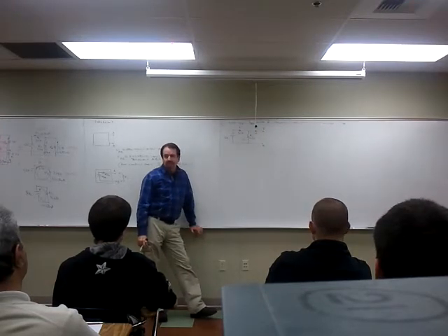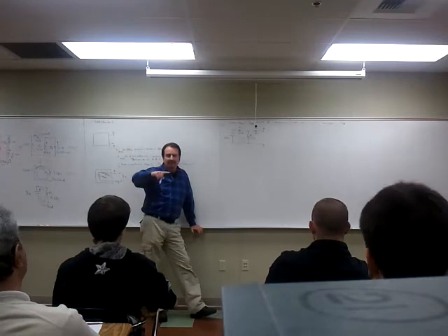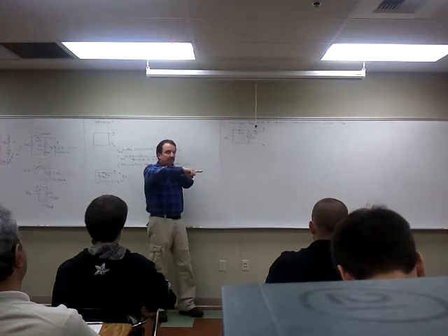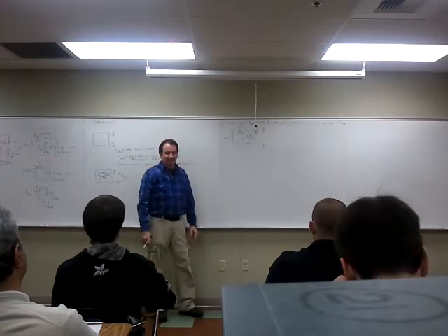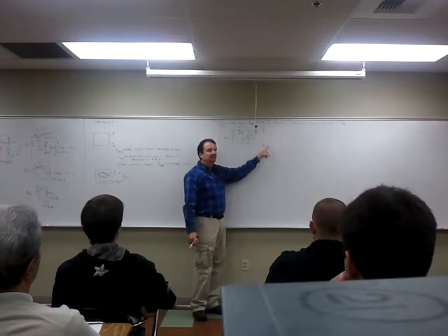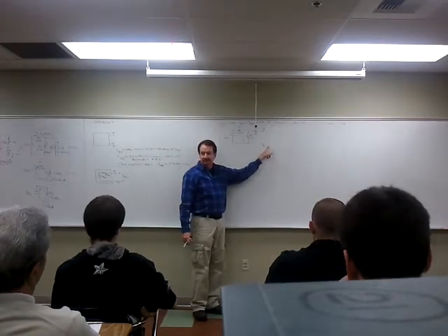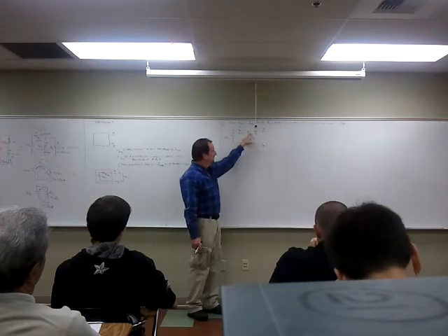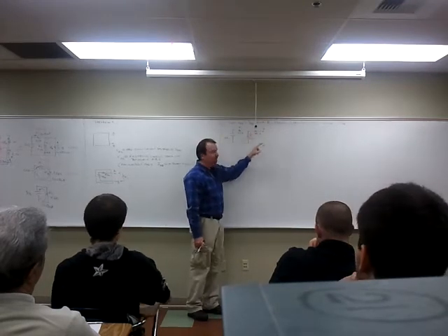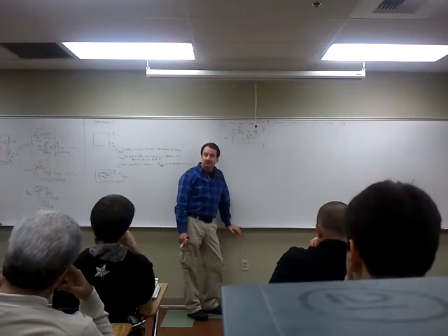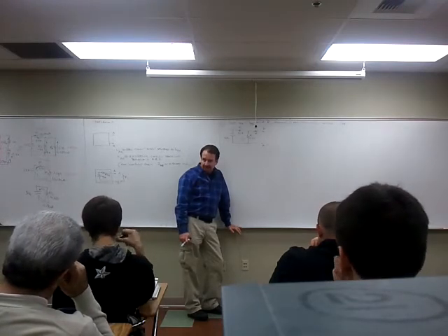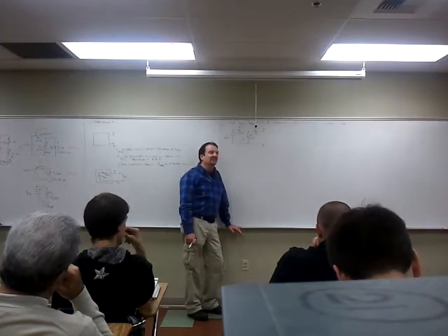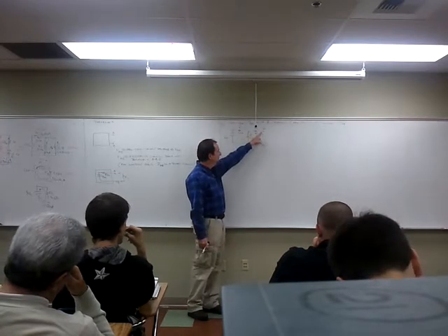That's a very important principle in all of electronics, all the things that you do. When you have a component hanging out in space, there is no voltage drop across it, yet it's an electrical connection from there to there. So can you electrocute yourself when the wire is hanging out in the open? Yeah, because as soon as you touch that, if you were touching this, wouldn't you now become a load onto the circuit? So you have to assume that the voltage there is identical to the voltage there. So again, in an open circuit like this, if zero current is flowing, V is equal to I times R. Zero current times any value of resistance is 0 volts. 0 volts means zero potential difference. No difference means the same. The same from here to here.